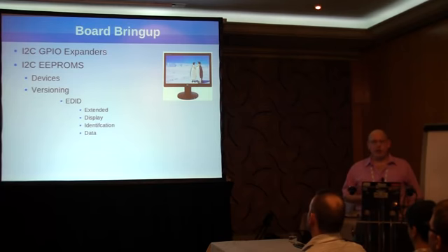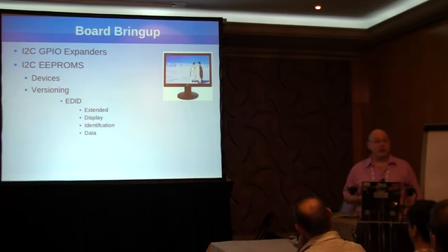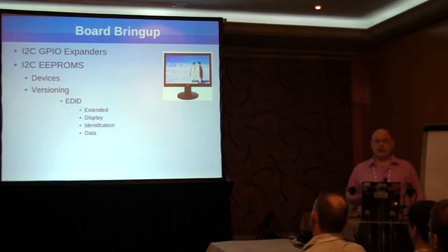I'm sure everyone here has tried to set up an LCD panel or a DVI device or VGA with X Windows at one time or another and had problems calculating the timing. Well, one of the things that's actually occurred over the last 10 years is virtually every LCD panel that you get actually has an I2C EEPROM in it. And it's actually programmed and referred to as EDID, or Extended Display Identification Data.